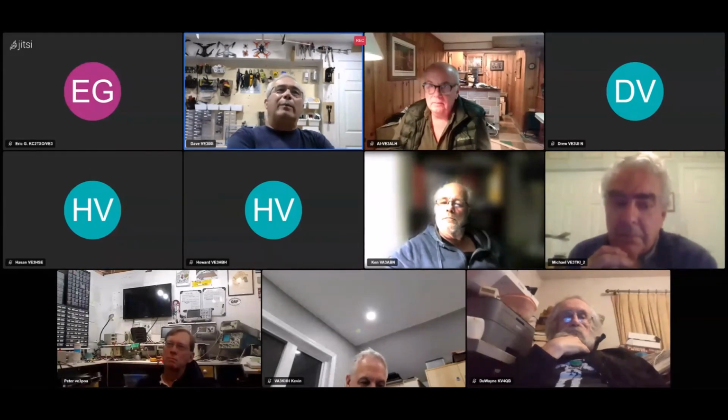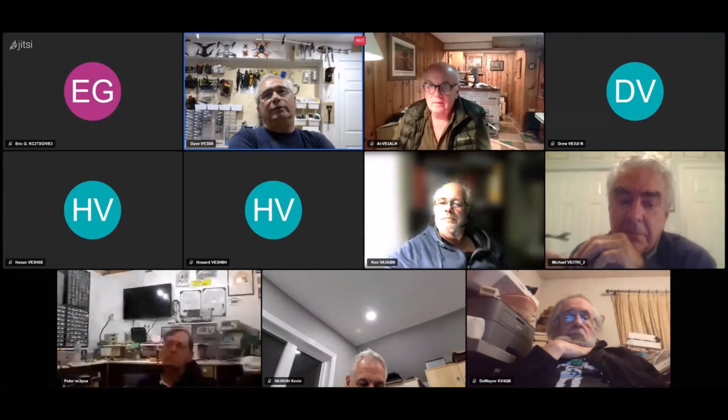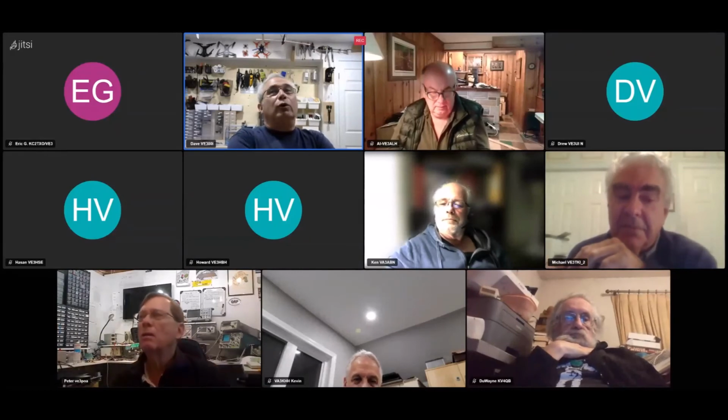I went back to Jason and said, I didn't realize this scope can do 50 ohms. He goes, that's a firmware bug. Upgrade your firmware. Sure enough, I upgraded the firmware, and that option disappeared. So you may have old firmware.